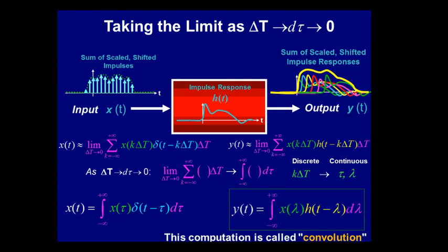This is what we came for. This is the convolution integral. This is the one that if I just threw this at you, you would say, what do I do with that? But now you know how to read that. It's just linearity. If the input is a sum of scaled delta functions, the output is a bunch of scaled, shifted delta function responses. Done.